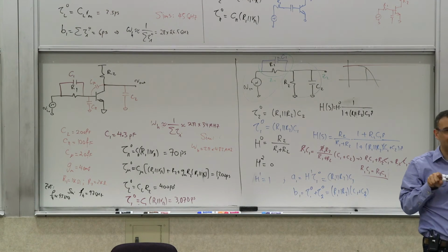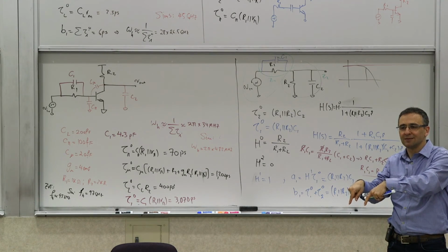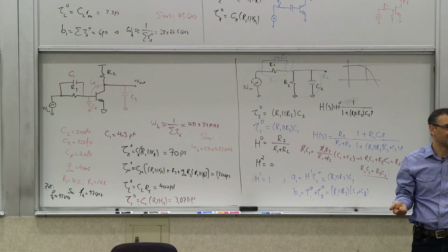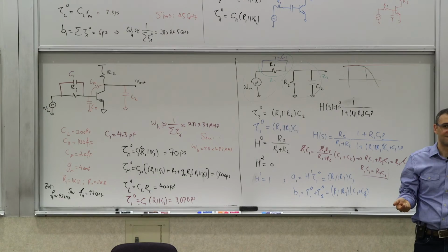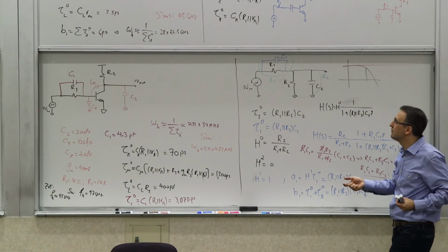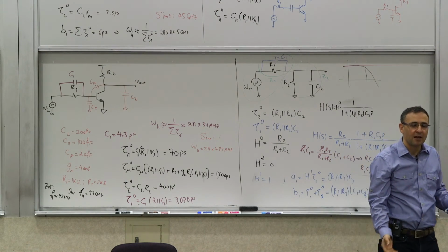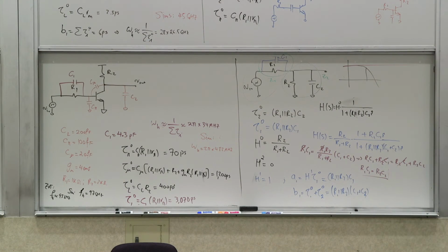If Z1 and Z2 drop at the same rate, then that ratio is not going to be affected. That's what's happening. Does it make sense? They both become smaller with frequency at the same rate. Now, this is used in oscilloscope probes and all that.